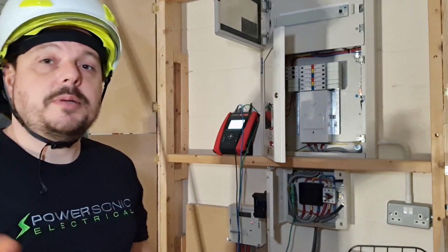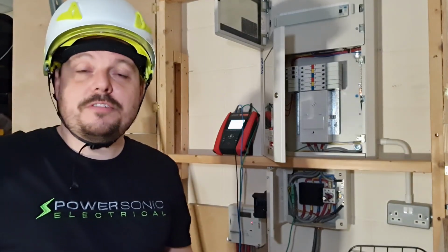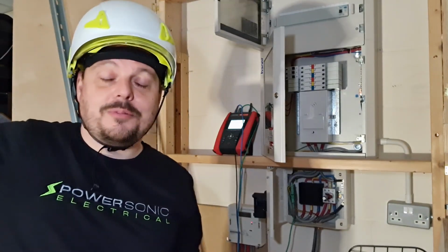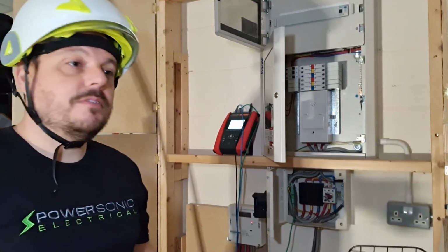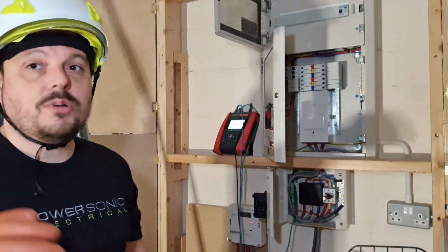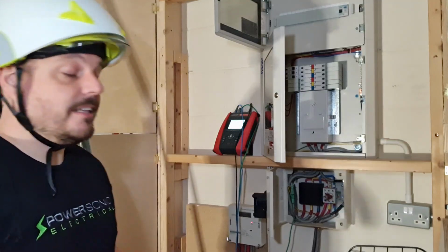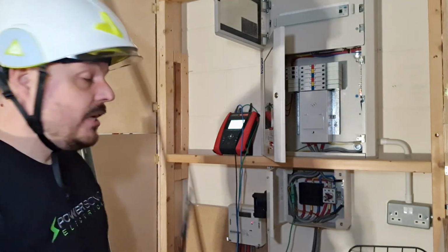but the DNO since then, I've been messing about. There's a new Screwfix and Toolstation opened up just around the back, and I think they've been messing about with their supply transformer and whatever's been going on there, I don't know. So it's affected the values in here. Yeah, so that's how Ze.